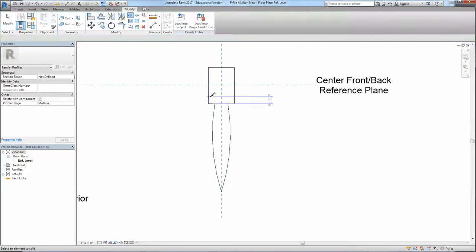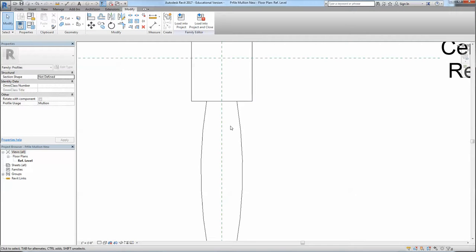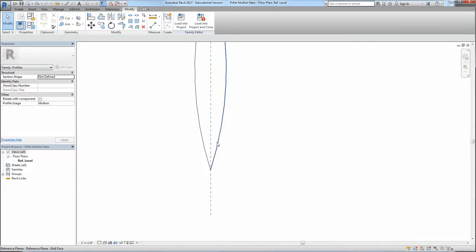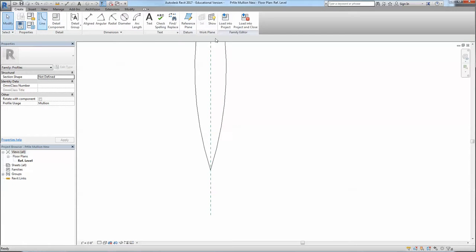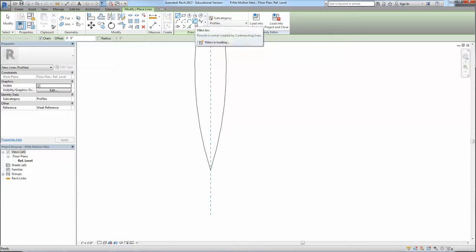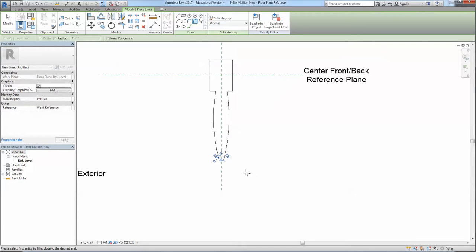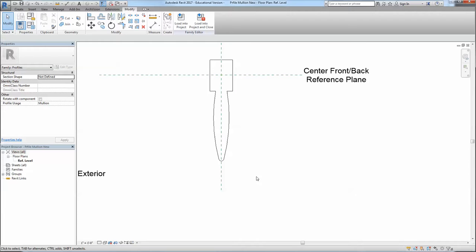I can break this point, as you know, and trim these guys. So it's actually one closed polyline. I can do a little detail curve here, so I can go to the lines and use the fillet option to select these two and make a nice kind of curvy detail at the end. This could be a beginning stage of a bigger detail that you can draft afterwards on top of it.